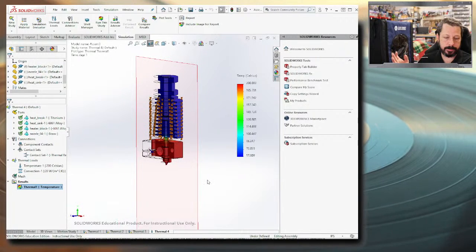So hopefully that gives you the last little bit. We've talked about this stuff before, but what I'm thinking is most of the time when you have printer troubles, it's a clog of some sort. And so maybe this little bit of knowledge will help you figure out how to get rid of the clog, or remind you that, oh yeah, maybe the Bowden tube is not pushed in all the way and there's a gap between it and the nozzle, or something along those lines.